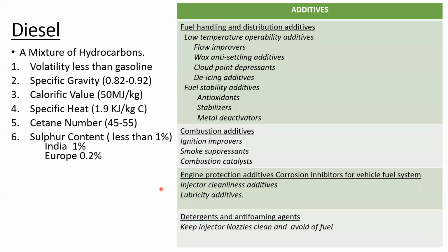In the petrol engine, they measure different chemical compounds, like carbon monoxide, carbon dioxide, and water. In diesel engines, they do not measure that, because they only measure how much smoke is coming out. We call it the K factor. From the K factor alone, they find out whether the combustion is good or not.